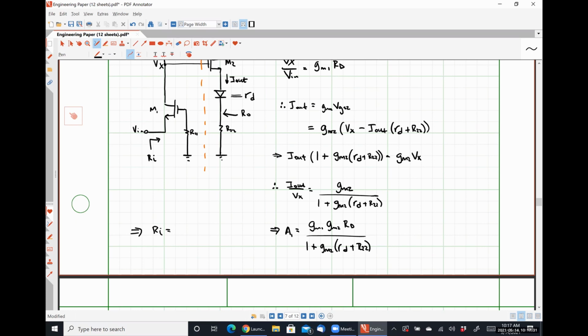It should be 1 over GM, right? Because we were looking into the source terminal. Yeah, so I had a total brain fart when I was kind of coming up with my notes. Thank you. So yeah, 1 over GM1, which would typically be pretty small. So it makes sense that we need to boost it by some large amount, okay?